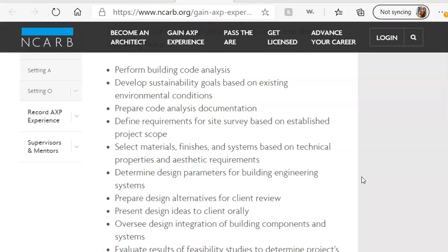And then some of the other things is just understanding what the materials will need to go in the building, maybe what systems are there existing, where the structure is, what you're going to invade, and how you maintain structure, and if your roof slope is appropriate, and if you need more insulation, or what the requirements are to keep the building protected from the outside, and keep water out of the building. Understanding what kind of glazing you want, which is just the glass or anything that is transparent in the building. You need to understand what's the difference between different materials.